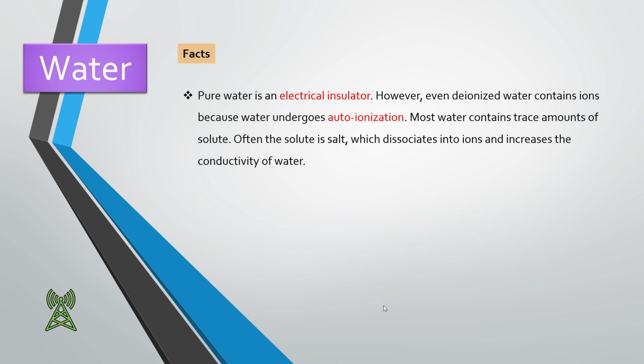And we never see that it is an insulator anymore in our field of pharmaceutical production. Small solutes are always dissolved, and we get a controlled conductivity of the water for our purposes. And we will see all those parameters according to the official compendia, how to regulate this parameter of conductivity.